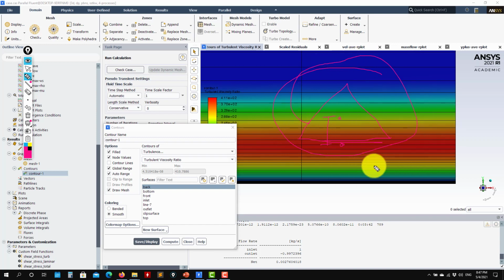Okay, when doing your mesh, try to get a good transition in your boundary layer to avoid this error. This will add dissipation, and it will be pretty severe if you have that here. For instance, you have the cell center here, and then you go like this. See that you are interpolating values from here, and here we are already close to the wall, to the viscous sublayer. But see that you will be introducing some turbulent viscosity in your viscous sublayer due to the fact that you are not controlling the transition. So be careful, those are the issues with meshing.